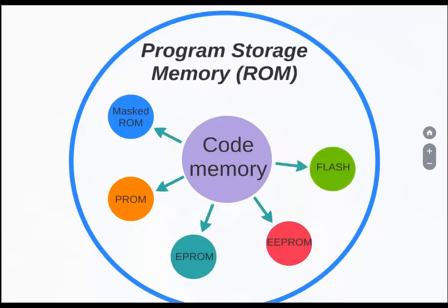Flash is the latest ROM technology that we have. It is actually a variation of the EEPROM technology. Here, the flash memory is organized as sectors or blocks or pages, and the flash memory stores information in an array of floating gate MOSFET transistors. The erasing of memory can be done at sector level or page level without affecting the other sectors or pages. Each sector or page should be erased before reprogramming. The typical erasable capacity of flash is about 1000 cycles.